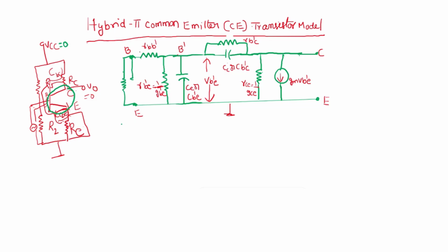like this, R1 and R2. Okay, here from the collector to the ground you have to keep another resistor called RC, because this RC also goes to the ground. This is the circuit. These are the external resistors, and this total part from this to this is the internal circuit of the transistor, remember. All other external connections you have to connect to this equivalent model.